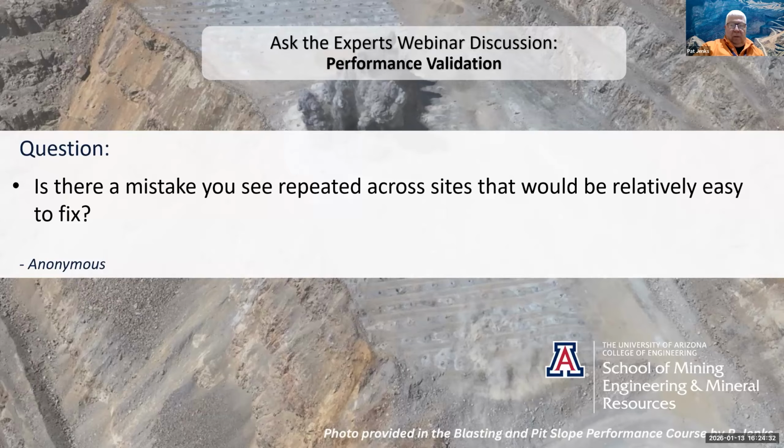You need to be discussing the pattern design. There should be a lift map layout for each bench that identifies where the pattern breaks are, includes the geology. You could talk about things like the timing and points of initiation, directional shooting. Historically, how have things performed? It should be including as part of that blast master planning process on the lift map, all faults, lithology boundaries, alteration boundaries, geotech domains. I mentioned the blast hole layout and pattern breaks. We need to set this whole program up for success.